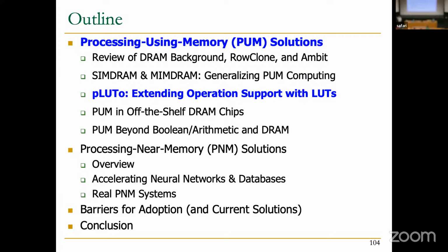And there was the PhD student that graduated before me. He was actually working on this, and he did a lazy coherence for processing using DRAM. Basically, you speculatively assume that you can execute the computation in DRAM, and then you track using some bitmaps which words the DRAM accessed. At some point, you compare against the writes that the CPU did, and if there is a match, you roll back the computation. That works for the computation, as you can mention later on. But for the atomic part, we didn't check.